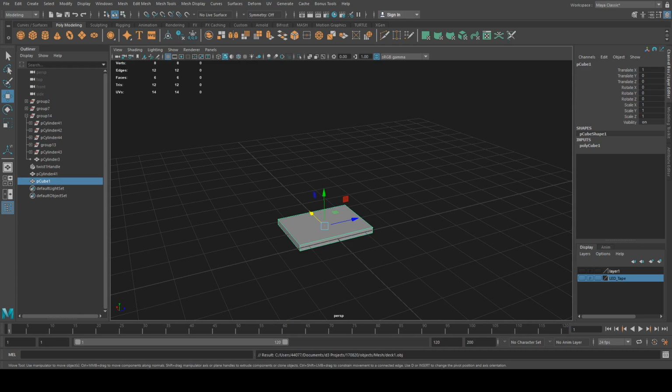Okay. Now, for fun, we can actually turn these into lifts. So I'm going to add an open layer. And I'm going to open each of the setups and also open my open module. And I'm going to drag from here, from the open module, to my offset. And I don't need offset X and Z, I just need offset Y. So I'm going to remove X and Z from each of these. Last one.